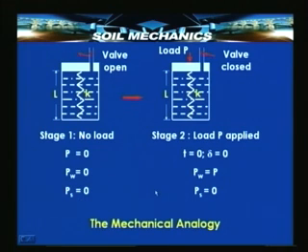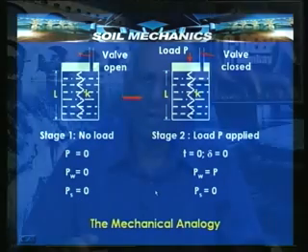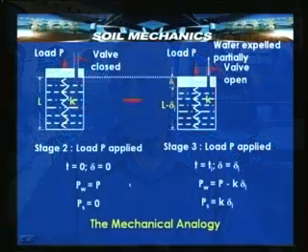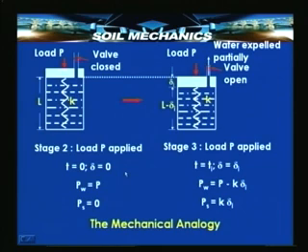This is the starting point, and now in order to simulate this consolidation phenomenon, we will open the valve. Once the valve is opened, water will start flowing out, and then we will see how the load gets transferred to the soil. So, this was the second stage where the load P was applied, and at t equal to 0, water was carrying the full load and solids were carrying no load because the valve was closed and there was no flow.